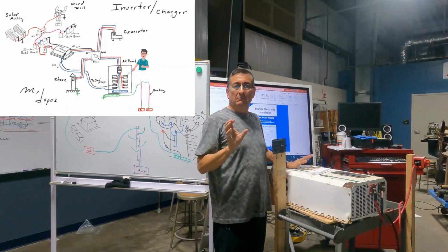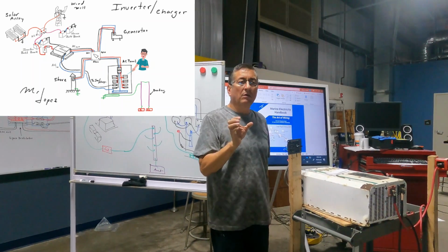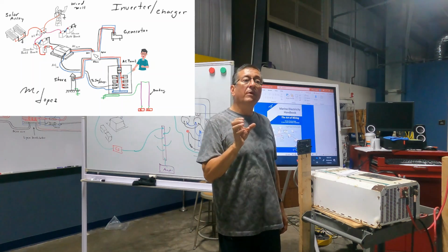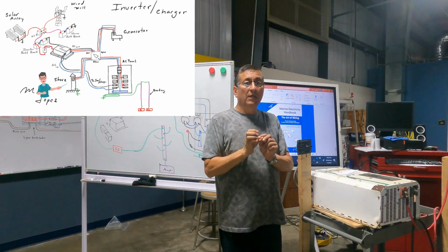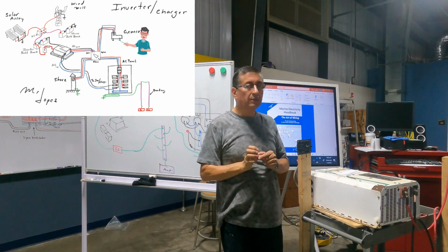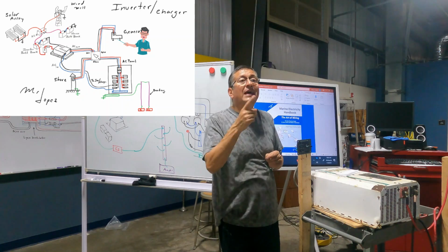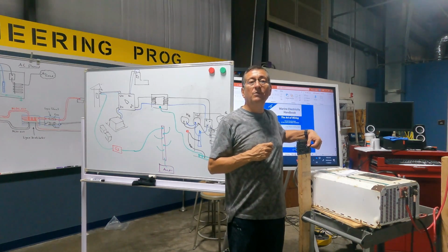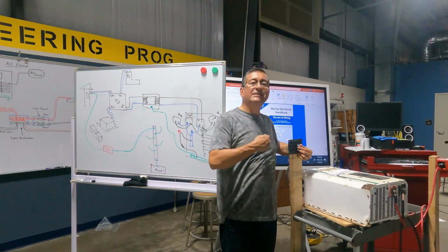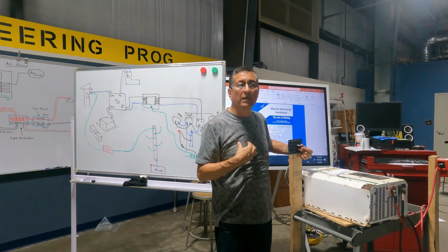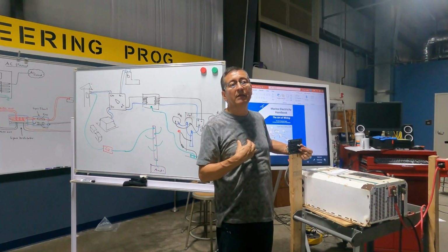That's it. In other words, in the traditional AC panel until today, I have power coming from the shore power, coming from the inverter, or coming from the generator. Three sources of power. That's clear? But that decision depends on me, because I select this one or this one or this one. This is my decision in the traditional boat until today. Everybody follow me, guys? All right.